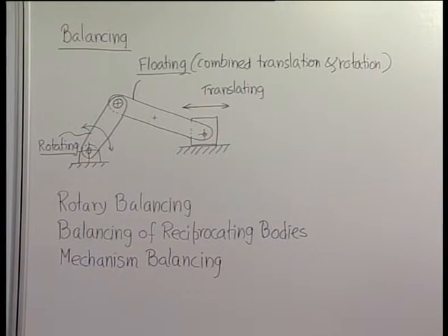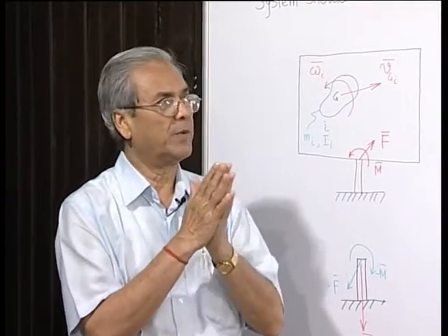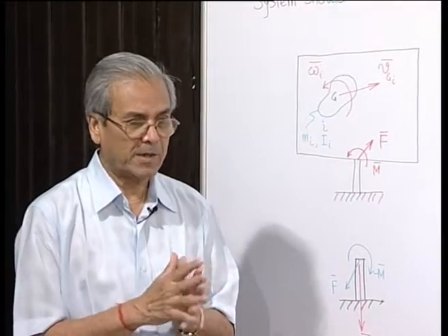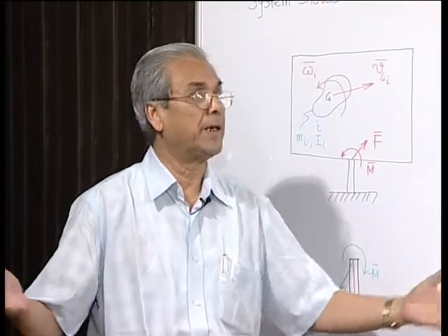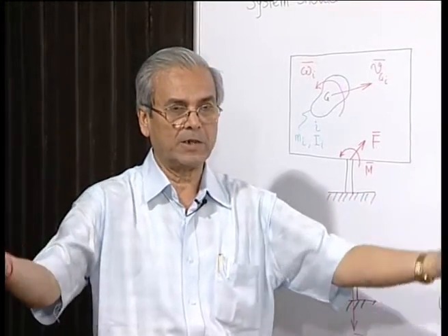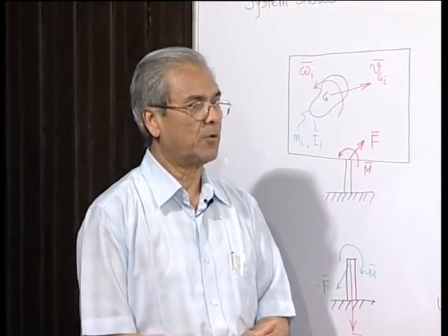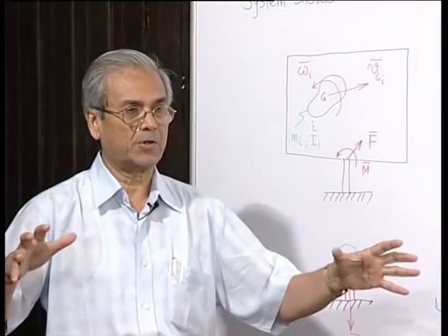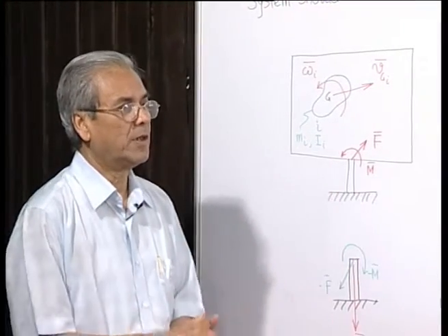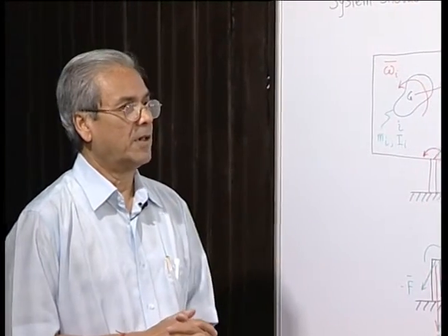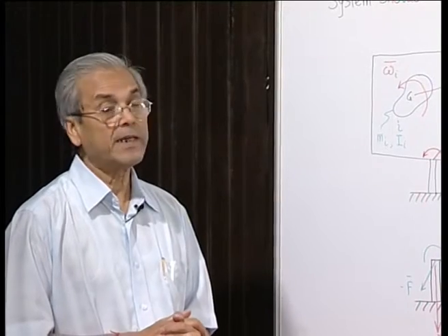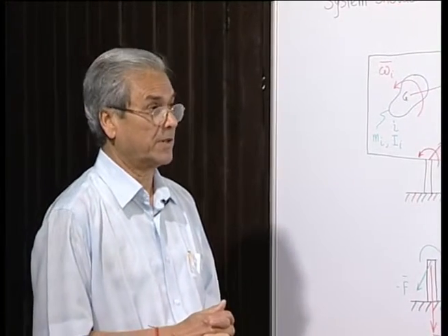These balancing problems which we will take up now one by one are a theoretical way of doing it at the design stage. Sometimes what happens is that after the machine is built, if it is very big and is placed on its bearings or on its supports, the deformations etcetera due to its gravitational pull can make the system distorted from its original idealistic design, and it may give rise to some unbalanced effects.